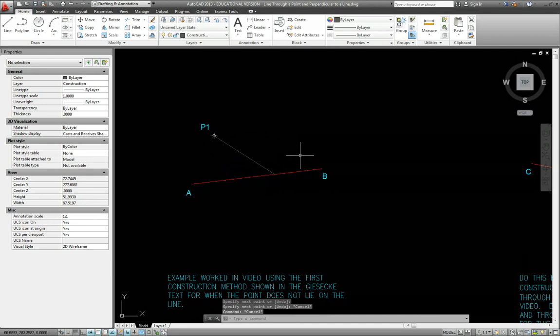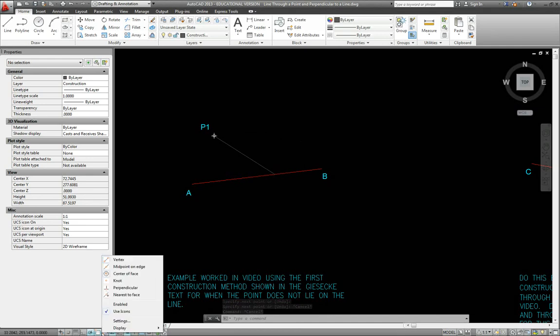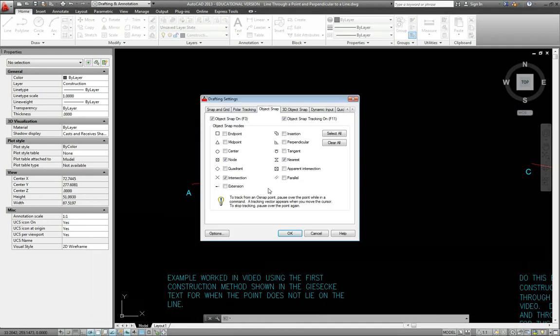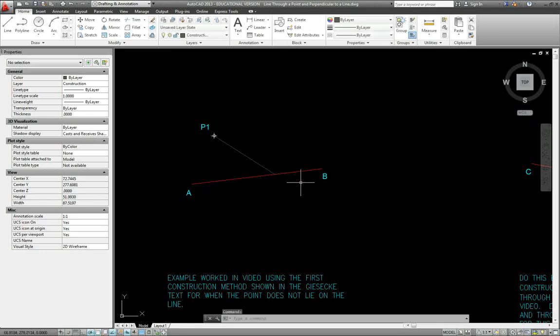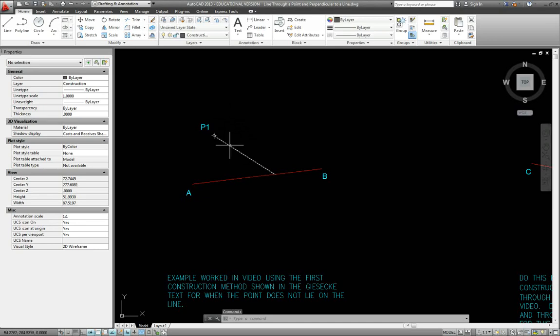Of course, that line has a midpoint. You want to make sure that your midpoint snap is turned on for this, so I'll turn on my running object midpoint snap. I could also have done a one-time override, but midpoint and endpoint are ones that you use frequently. So from the midpoint of this line, I want to draw a circle. When I see the triangle for the midpoint snap, the edge of the circle will go to the endpoint of this line.